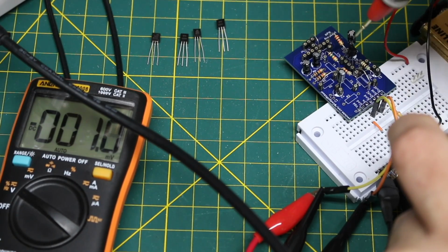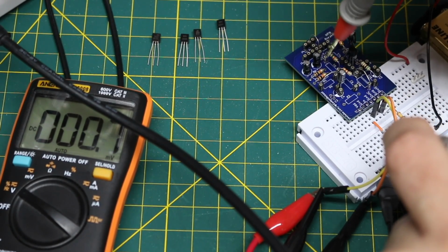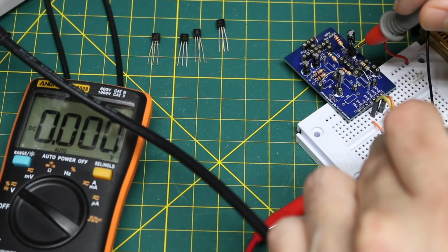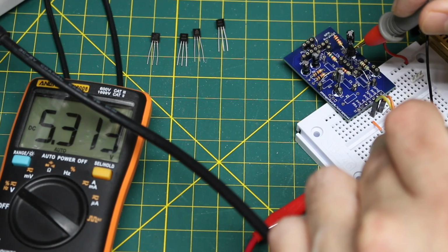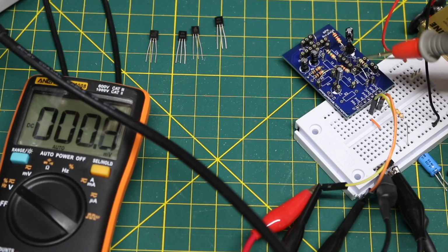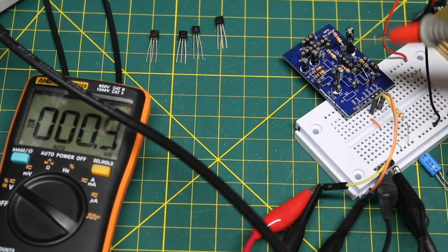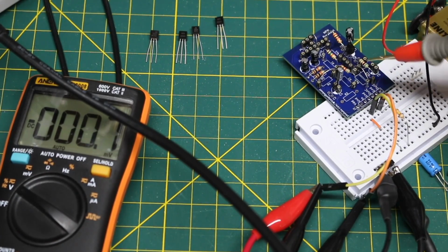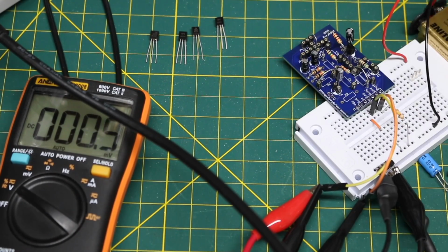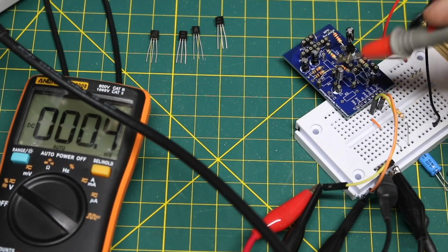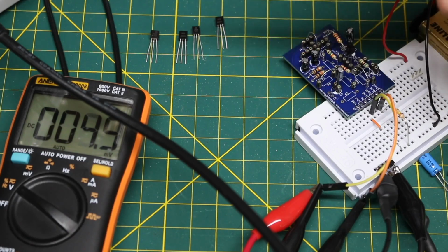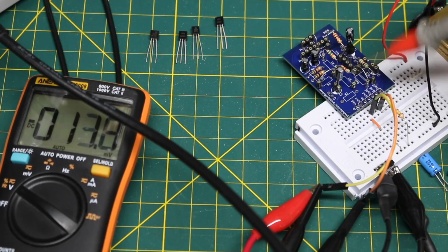looks good. And our base voltage, 1.6 volts, and the collector, 5.3 volts. We're expecting 5 volts, but give or take a couple of hundred millivolts from calculated. As long as it stays relatively stable as we switch transistors, we're just looking to get relatively centered between our voltage rails, or whichever two extremes we decide to calculate between, so that we have maximum headroom with some variance